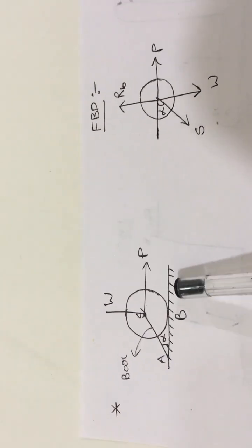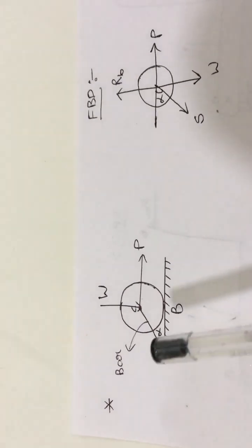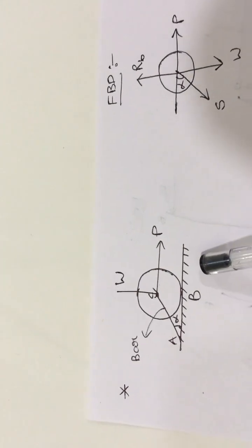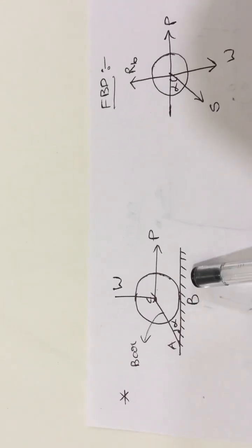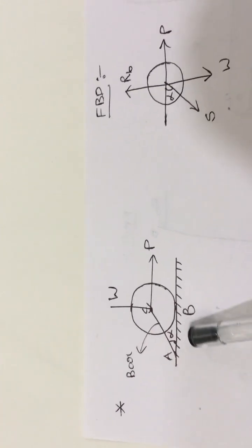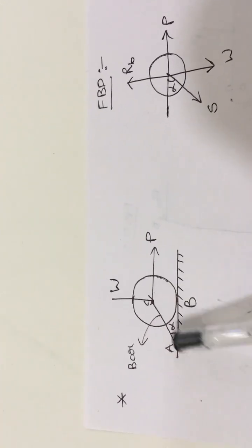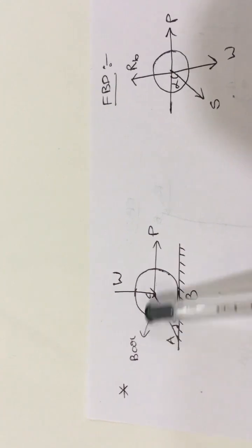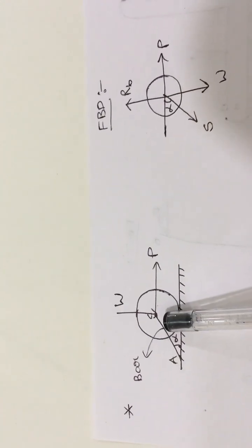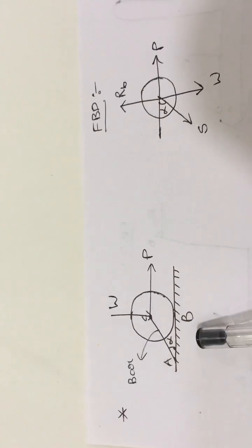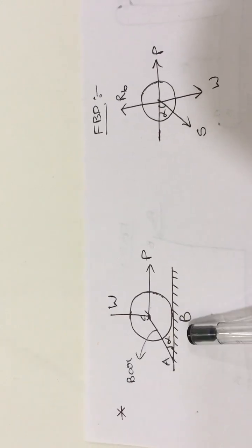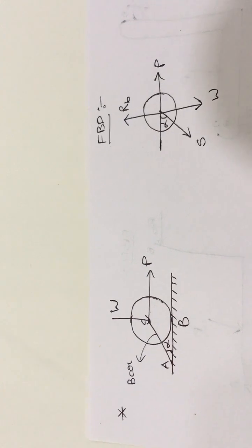This is one of the diagrams which is given in the question. Now here see the diagram. Here how many supports are there? Here the dashed line is the indication for the fixed support. So here one support is there, and from A to C, which is nothing but a bar. A bar is also one kind of support. So here two supports are there. So by removing these two supports, you will get the two reaction forces in the free body diagram.